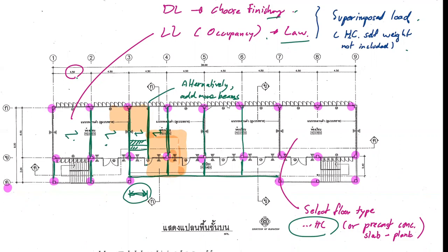But in fact, if we talk about choosing something, even if you use metal deck, you may choose not to have the composite action as well, because some engineers do that. Why? Because they're not really sure about the shear connectors, maybe, or they don't know how to handle the problem. Which is kind of sad, right? The capacity is there, and if you truly use this, see how much money we can save.